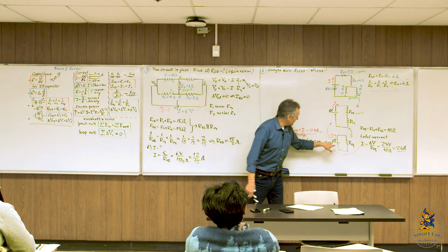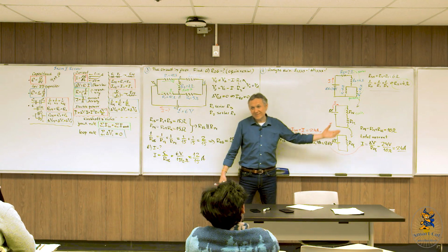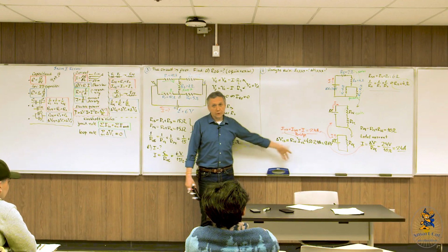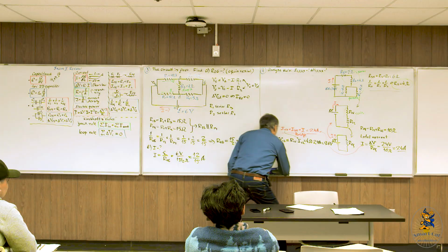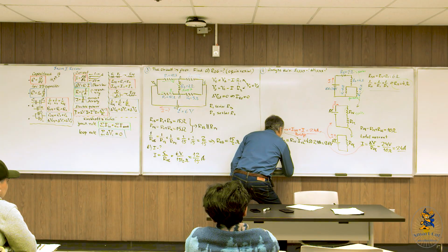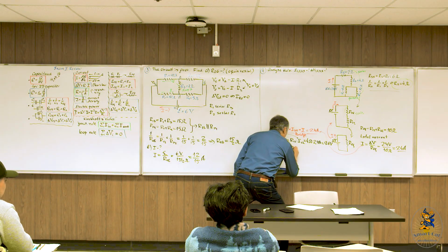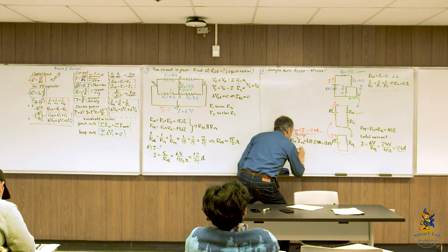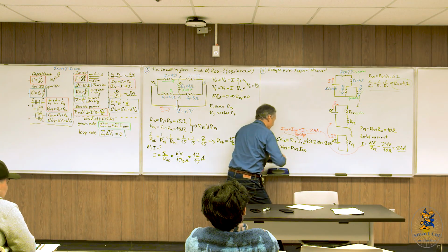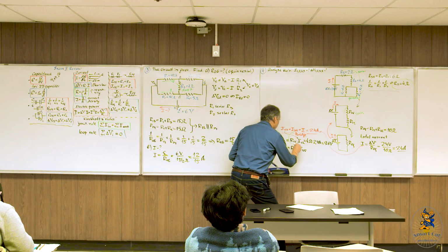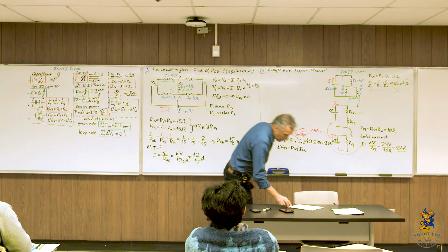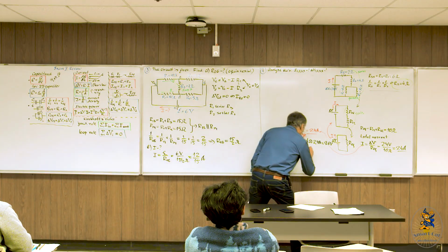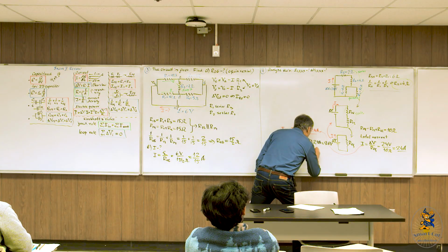Of course, now the potential difference across R35 you can find using two options. Either 24 minus that, but I still prefer to use Ohm's law. But again, it's up to you, right? So delta V35 will be equal to R35 times I35. And again, this current comes from the bridge. So you can plug in and you will get 14.4 volts.